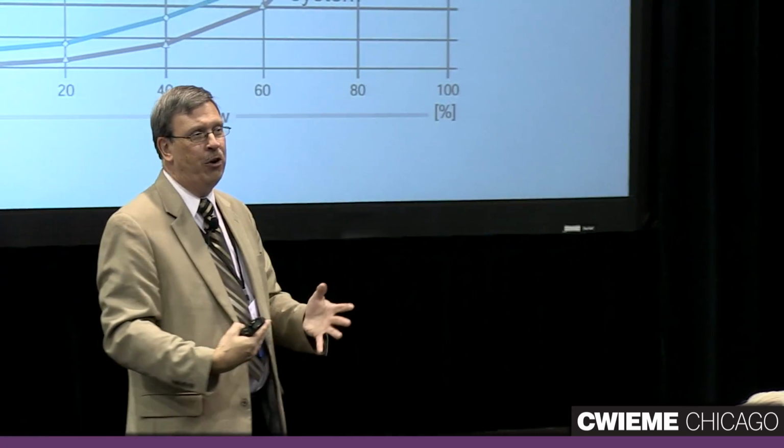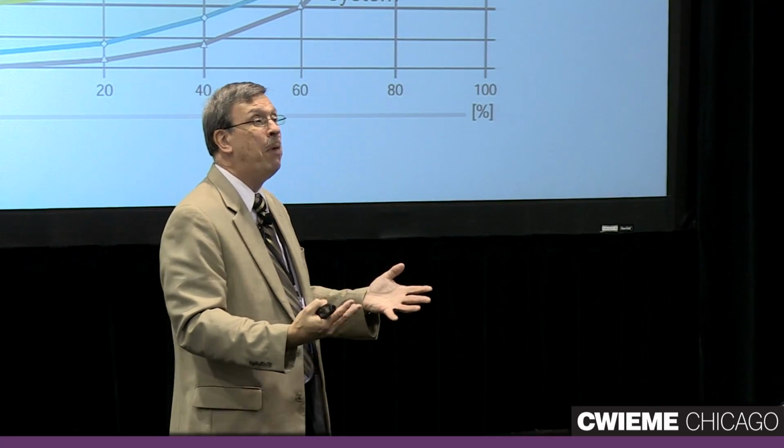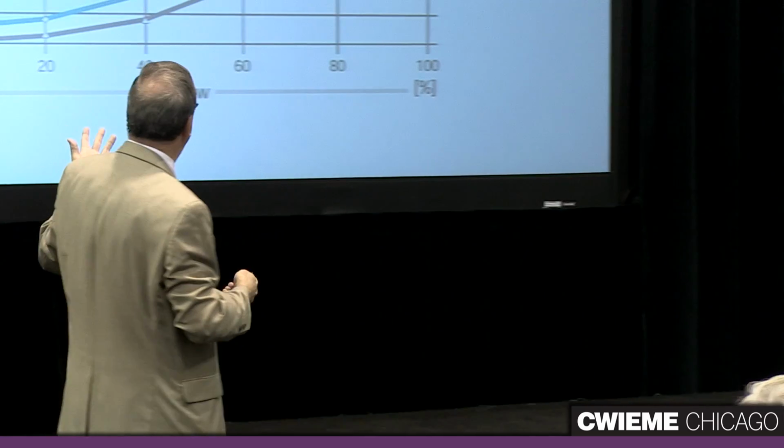And so by putting a drive in there, by reducing the speed of that motor, you can reduce the flow, and the torque goes down with that. Because torque is a squared function and power is a cubic function, if you're running at, say, half flow, the torque is going to be 1/4, and the power is going to be 1/8. 1/8 of the power. That's what you pay for, is that power. And so there's a huge energy savings there, huge payback. Usually within 6 months to a year, you've already paid for the drive. And after that, it's like free money. And everybody likes that stuff.